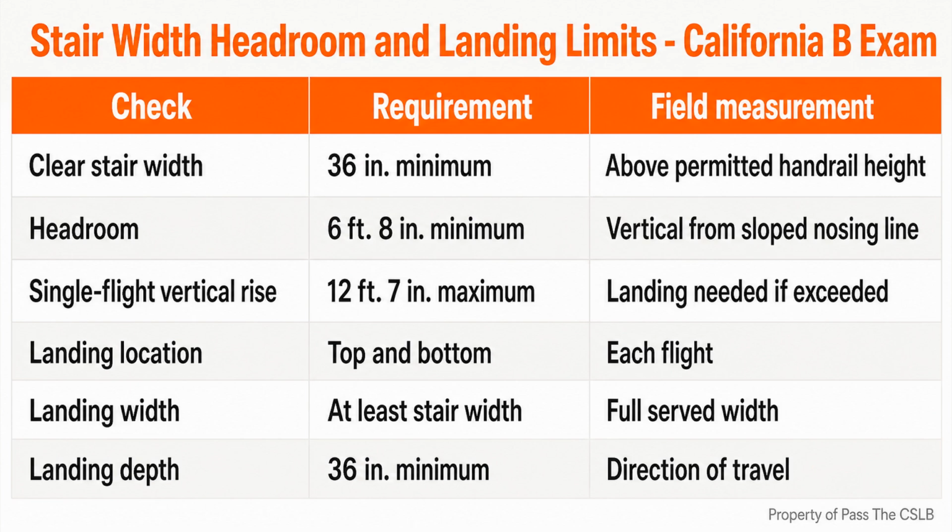A stair can have perfect risers and treads while still losing required clearance or landing space because framing, drywall, finished flooring, or a door condition changed around it. The practical supervision point is coordination. The stair opening, floor framing, wall finish, ceiling finish, and landing surface all affect the final measurement. A rough opening that barely works before finishes can become too tight after gypsum board, trim, flooring, or a soffit is installed.